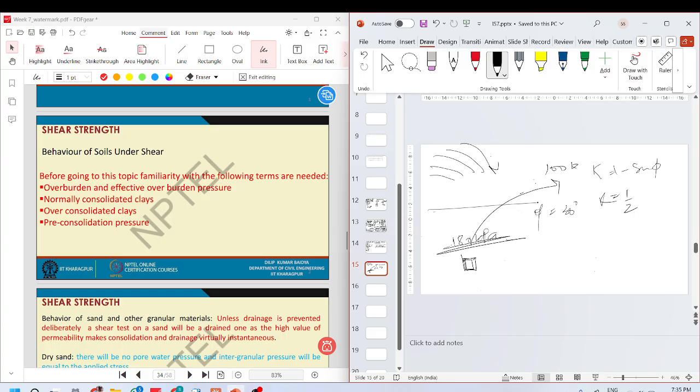But let us say that I build a building here and add 100 kPa more. The loading will increase to 280 kPa, for example, and then the new consolidation pressure is 280 kPa. Basically, the pre-consolidation pressure is the maximum pressure on that element of soil that might have fixed the structure of this soil in a particular way. Okay,